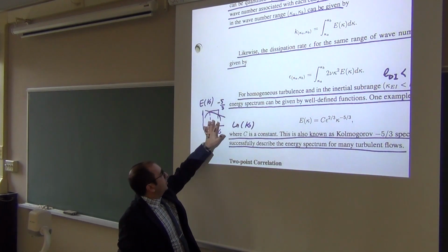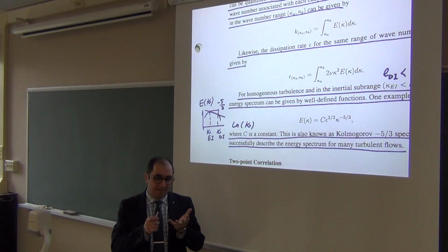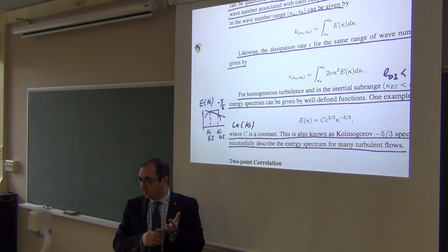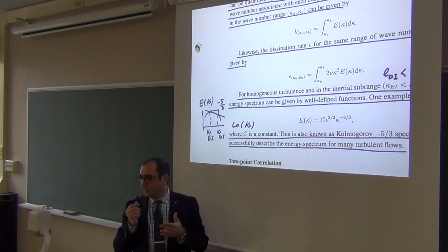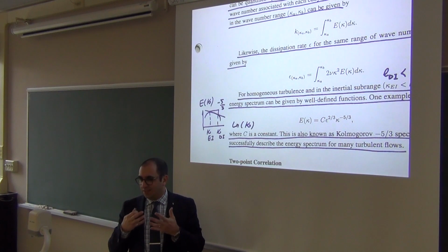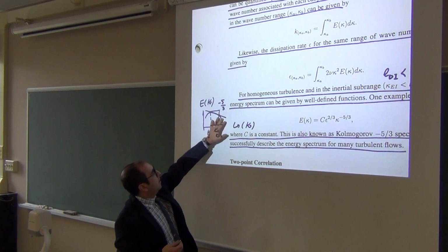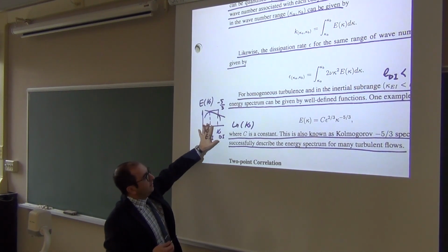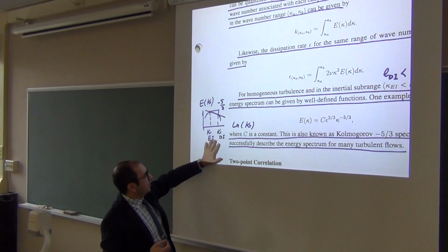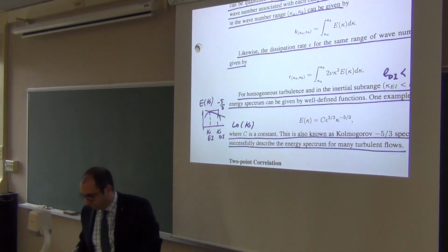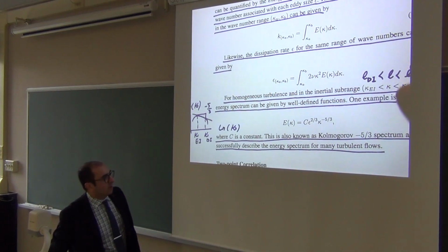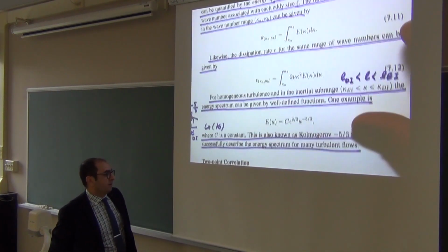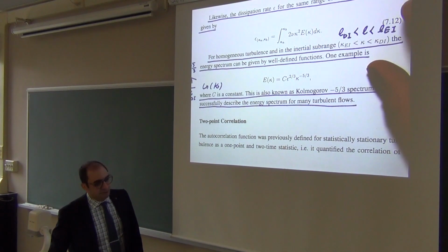We fit these shapes for heat flux, turbulent heat flux, Reynolds stresses, the normal components, the shear components, scalar fluxes. You can fit these energy spectra for any turbulence statistics of interest. It's a very broad topic, and people do it all the time. Any questions?